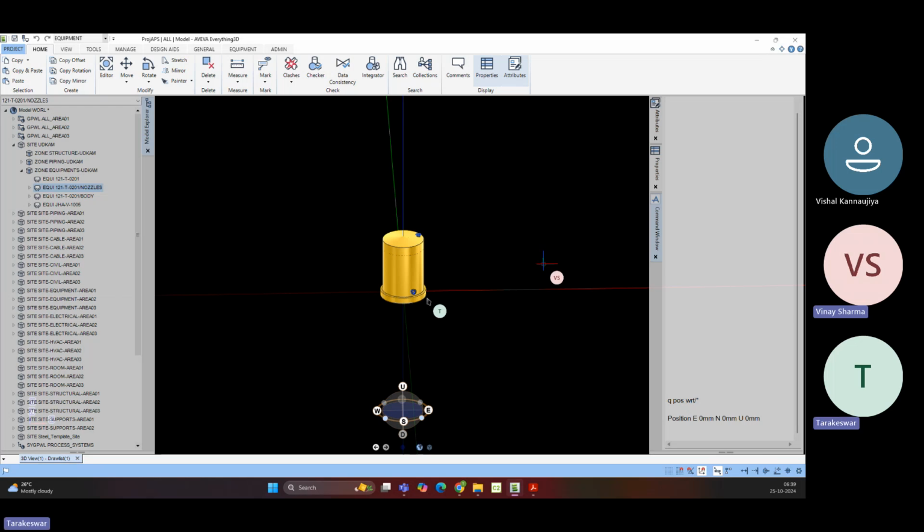That pump is not decided by us. That is the vendor's property. That's why we are not creating any kind of pumps in our industry. Normally, whoever has worked on site has seen that pumps will be installed by the vendor only. When the vendor creates the package drawing, you either create a 2D drawing or a dummy on the 3D model. Once the vendor provides you the 3D model, you simply place it over that and delete the previous model.